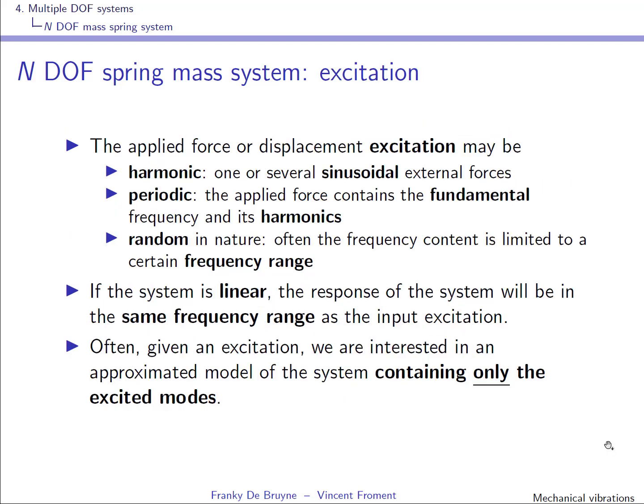Well, we know that the applied force or displacement excitation, it depends on the type of problem that you have, can be harmonic, periodic, or random. If it's harmonic, it's simple. If you look at the spectrum, it's just one spectral line. If it's periodic, you have a spectral line corresponding to the fundamental frequency, and then you have the harmonics. If it's random in nature, you have a whole frequency range.